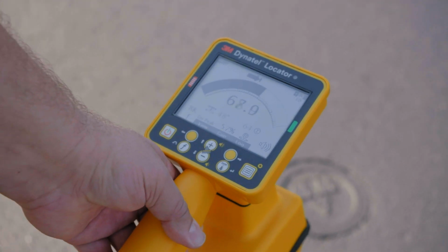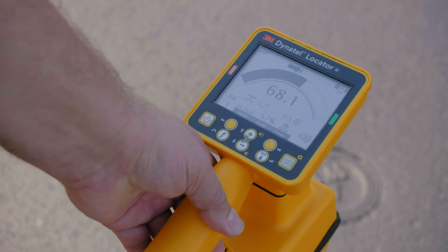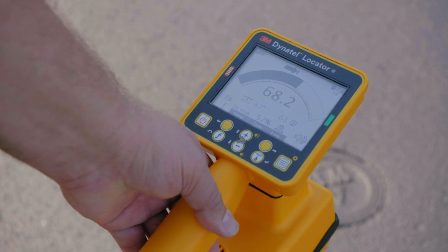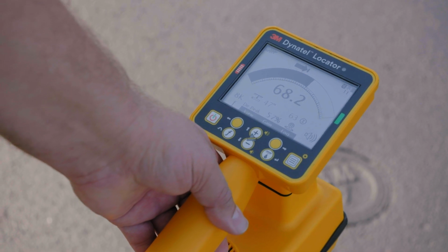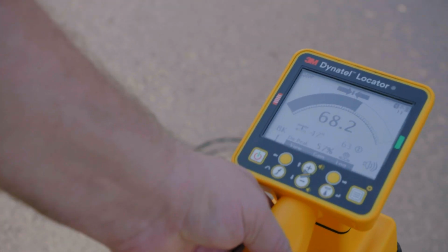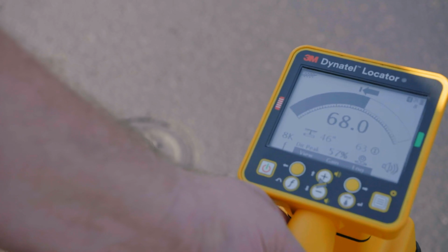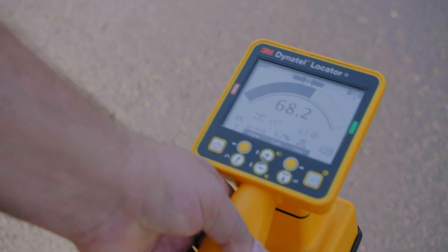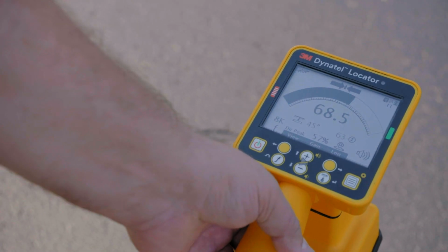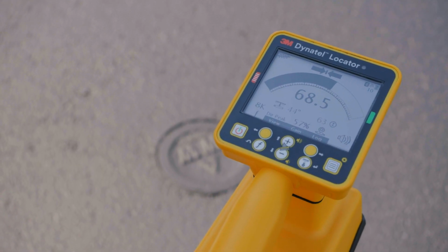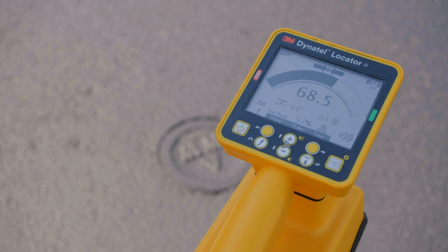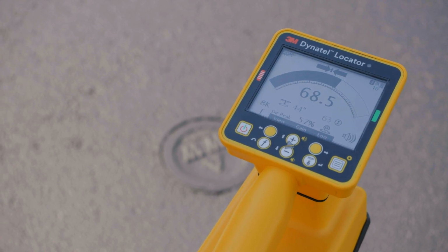As the receiver approaches the electromagnetic field from the left of the target path, an arrow will appear on the locating screen pointing toward the right. It is detecting the rise of the electromagnetic field surrounding the target conductor. As the receiver crosses the path of the target conductor, the arrow pointing to the left will appear, indicating the target has been passed. The middle antennas are now detecting the fall of the electromagnetic field.